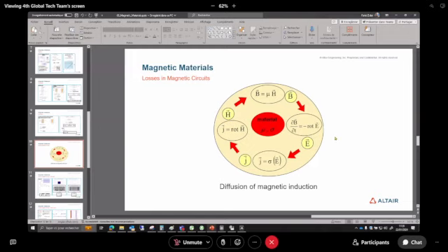If you remember, Faraday's law or Lorentz law. This potential, since there is electric resistivity, will create what we call eddy current, and this eddy current will create itself a magnetic field in opposition to the main magnetic field, and this system will be stabilized, and we will have anyway this eddy current.